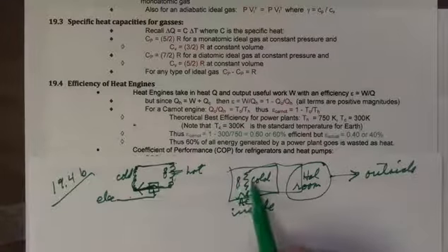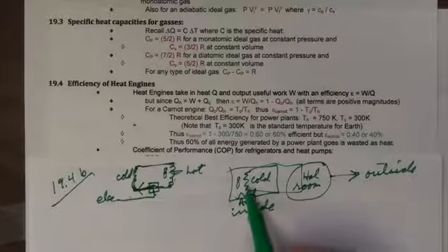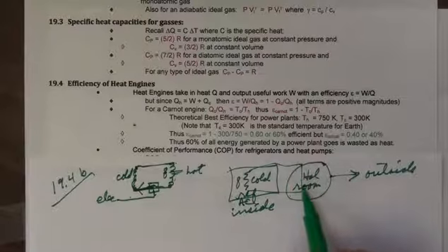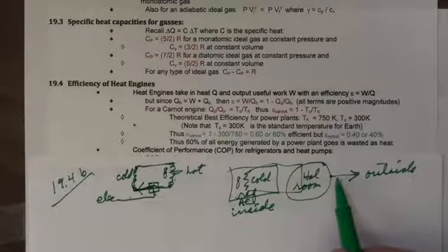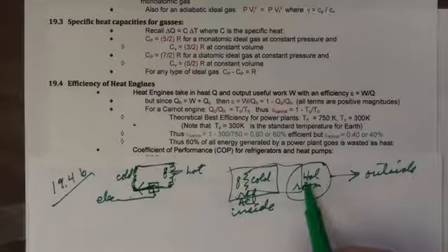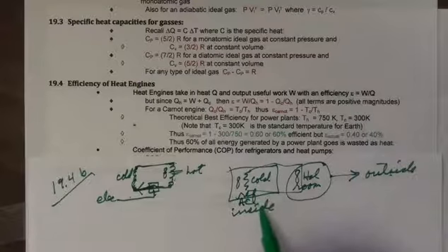And as the fan blows over these coils where the coolant is rapidly expanding, these coils are extremely cold, and of course that cools the air in the room. And then over here, we take it outside and get rid of that heat that it took on inside, blow a fan over it, blow the heat outside, and everything is nice because we get the air conditioned inside.